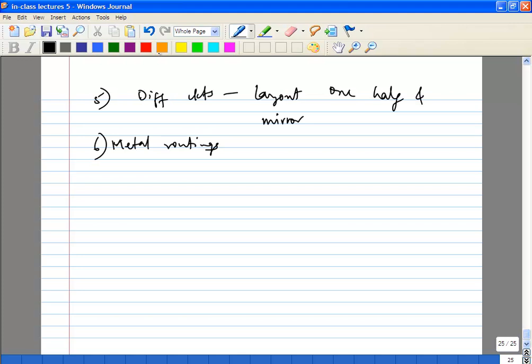And normally the way you would choose is, let's take the lowest metal layers. Because they have a lot of parasitic capacitance to ground, you don't want to route signal lines on M1 or M2.